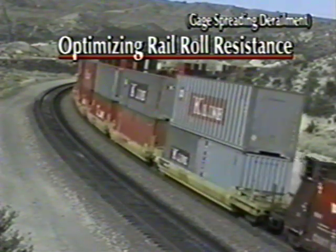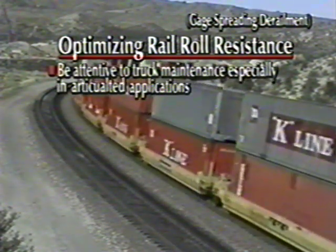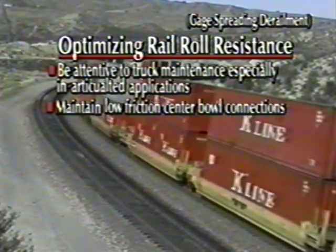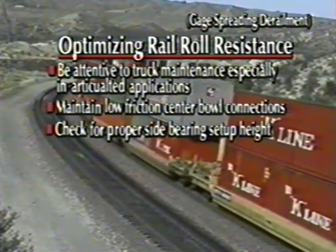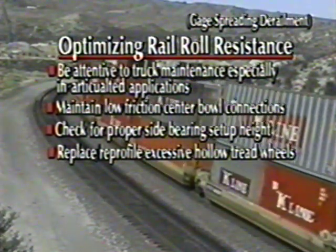Let's review the factors that can improve rail roll resistance, like paying close attention to truck maintenance on all rail cars, particularly those used in articulated designs, maintaining low friction center bowl connections, maintaining proper side bearing setup heights, and reprofiling or replacing wheels that develop hollow treads or false flanges.